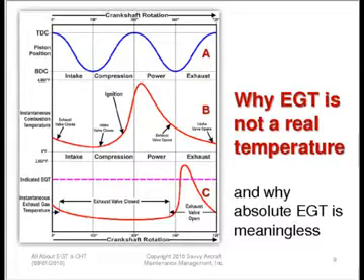That temperature is not really a gas temperature, as you can see. The only thing you can say is that it's the temperature of the probe. Wherever that probe finds equilibrium in the face of all of this rapidly changing temperature and rapidly changing flow, is what is reported on the EGT gauge.